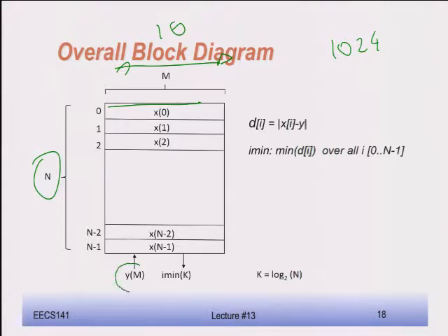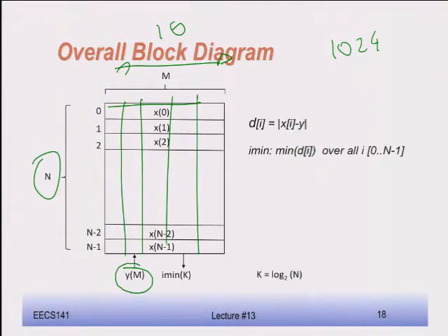So I apply my value y, which is going to be the same width as your memory array. What you do, like in any memory, is feed this through vertical wires to each of the cells. So the same value y goes up vertically, and you present it to every cell in the memory array. To give you a little bit more perspective, I'm going to talk about memory structures in one of the next lectures to give you an idea how you do this in memories.